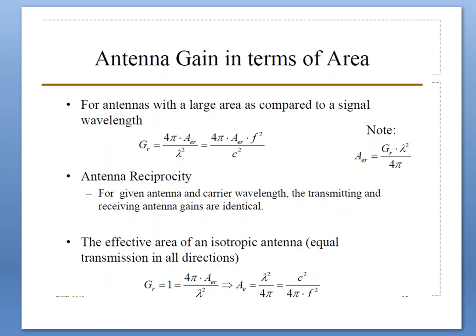How does the antenna beam vary with the signal frequency? How does the beamwidth vary with the antenna size? As we can see in the above equation, the antenna gain increases with decreasing wavelength, and the antenna gain also increases with increasing effective area. Increasing the effective gain is tantamount to focusing the flux into a more restricted cone angle. Hence, increasing either the signal frequency or the antenna size results in a narrow beamwidth.